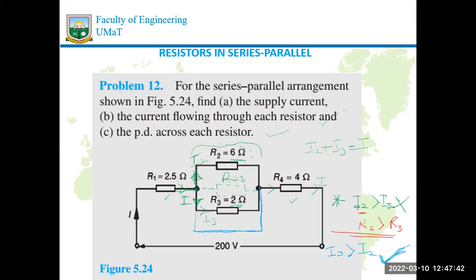Which means I connect a wire from this point to that point, and the wire has an approximately negligible resistance. Let's say the resistance is 0, the wire has a resistance of 0. The current I flowing, when it gets here, senses a resistance here, senses a resistance in the other branch as well, and notices that there is a part that has been provided of which I don't have any resistance. So the current will use that part because there is no opposition for it to flow.